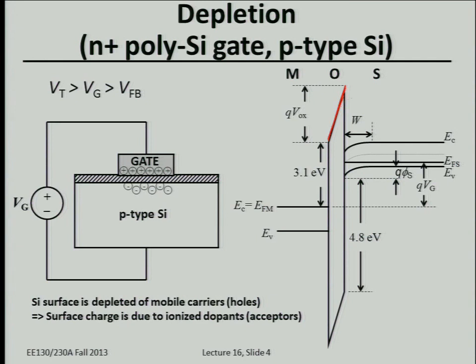Okay, so you're sloping upwards to the right rather than downwards to the right. Again, you're going to have some voltage dropped across the oxide, and again, the potential barriers here are 3.1 eV and 4.8 eV and so on. So the energy band bending will be sloped the other way. But now you actually have lots of room to bend the energy bands in the silicon, right? It's not like the previous case where there's really not much room for the band edges to move away from